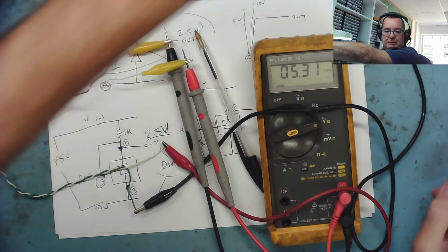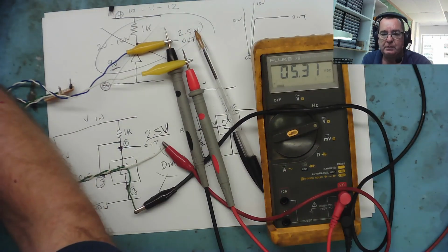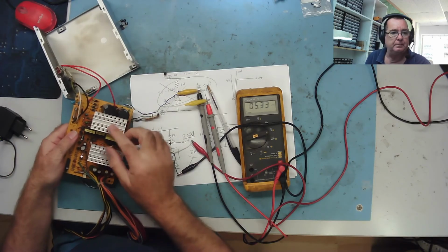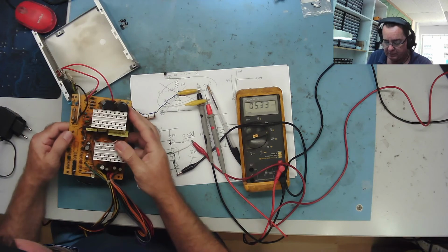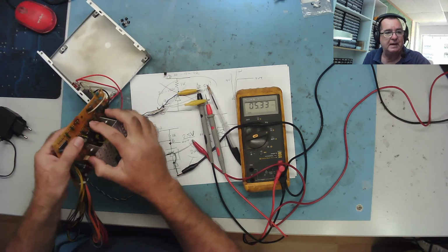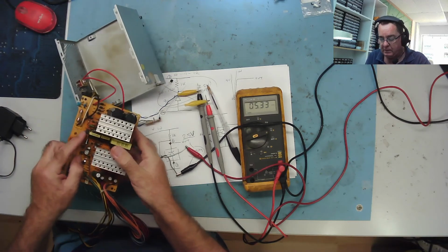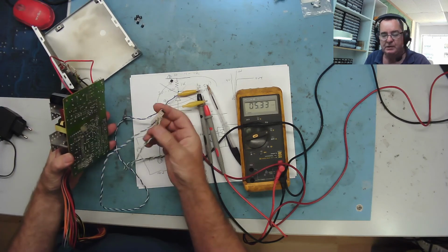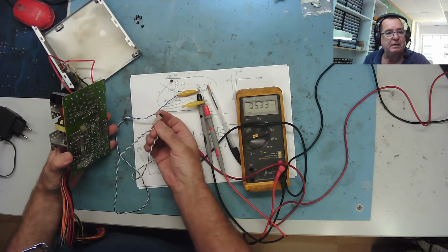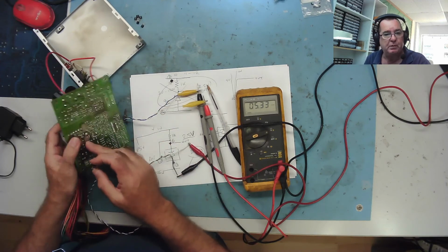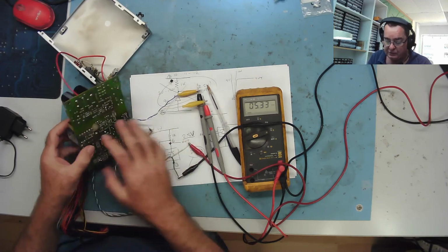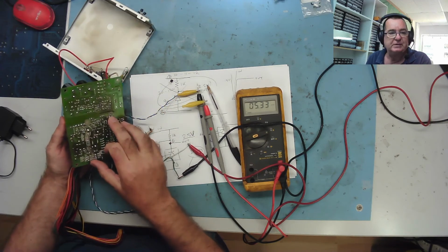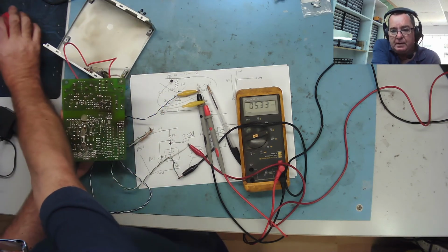We don't need the microscope anymore. Let me just zoom out. So this is the ATX power supply, and I said in here is a 431. Well, this little tester I've made, we can actually use this in circuit. The three little legs here, if I push them against the pads where this 431 is soldered, I should be able to test it in circuit. So let's see if we can do that.